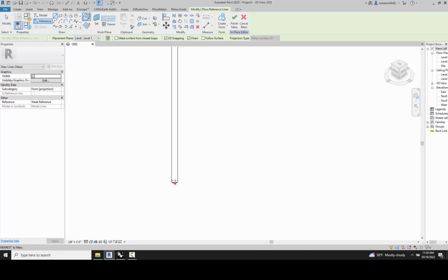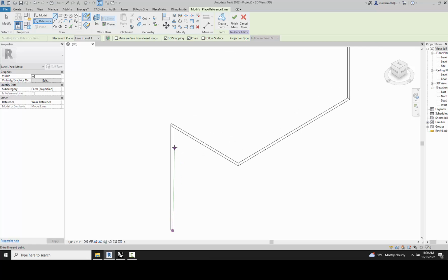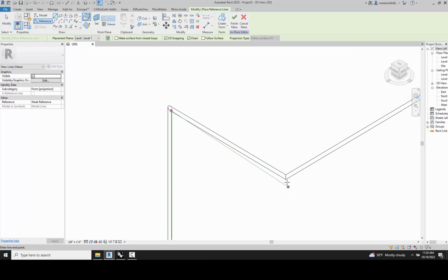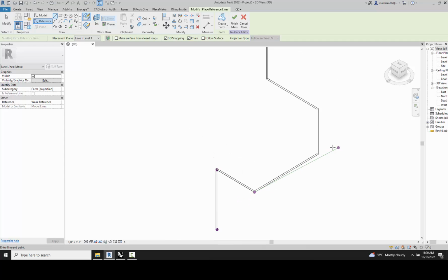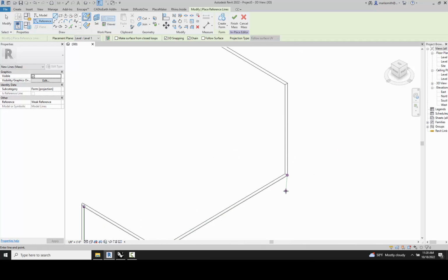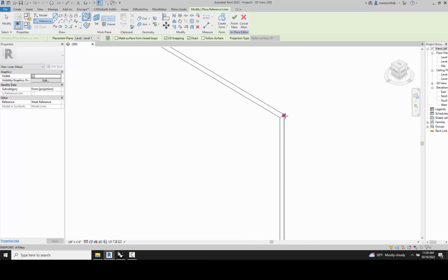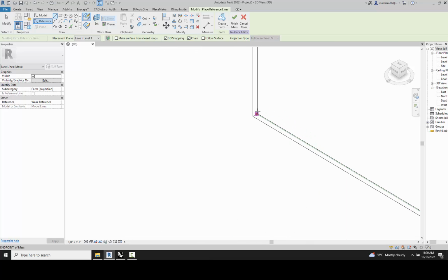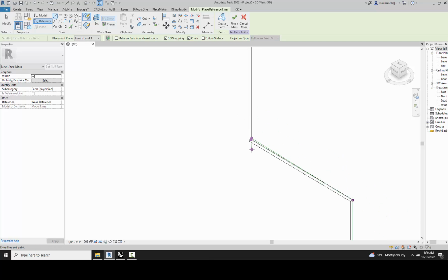If you wanted this to be exact, then I suggest in Rhino that wherever that sweep line is, you sweep like an edge line here around, so you can get the exact piece. But if you already have the cylinders, you can bring those in and just snap right to the edges. And again, it's not going to be exact, but it'll come in here and snap to those guys for you. Whoops. Let's go ahead and get that guy in there correctly. I'll delete that one. All right.